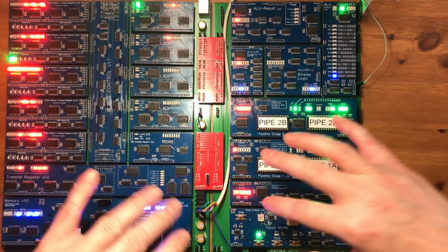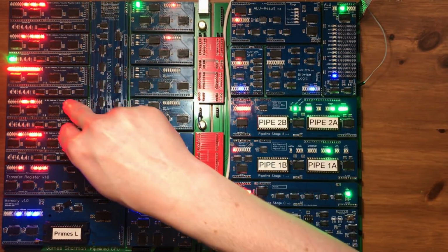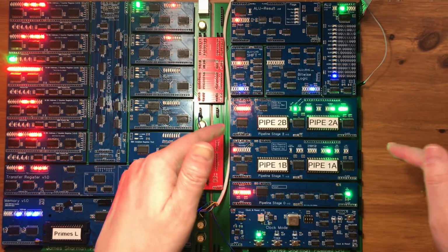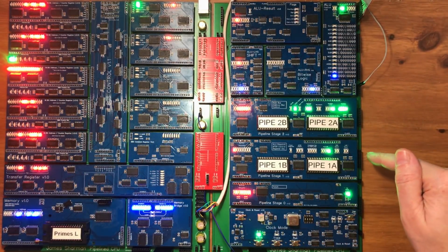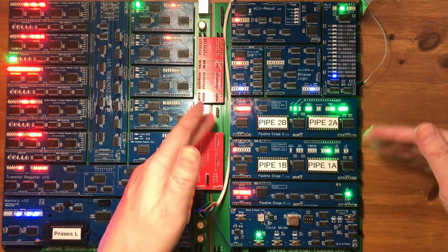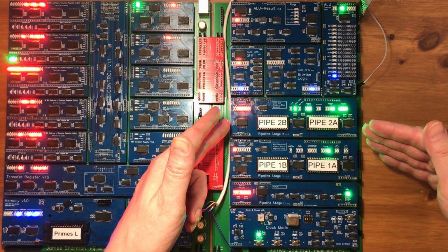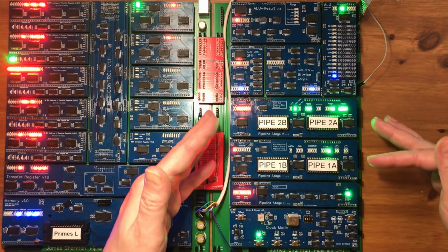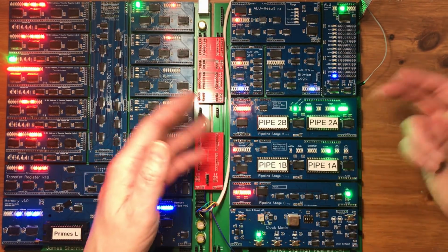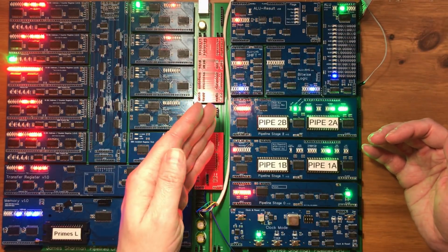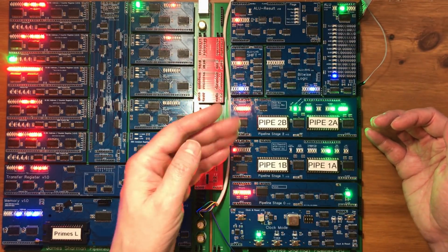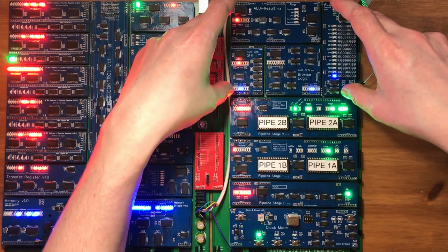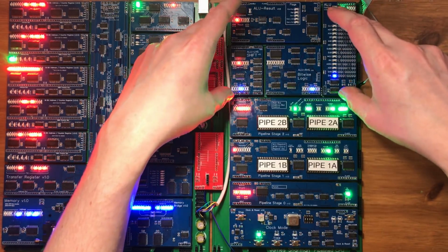Okay, but the two big changes is we would need another register over here. We'd need an extra control line into the pipeline in order to define when the interrupt was occurring, we'd need an extra output from the pipeline to reset the latch that was holding the interrupt status active. And we would need to modify the ALU to allow for preservation of its state.